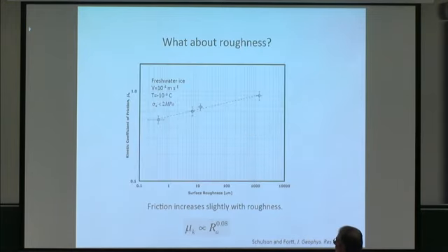There's again a certain universality. Roughness, yes, as I alluded to a moment ago, coulombic shear faults, that is, rougher surfaces, do exhibit somewhat greater resistance to sliding than a smooth, that is, a micrometer-sized roughness type interface. But this is not a strong dependence. Over 3 orders of magnitude, one gets the sense that the coefficient of friction is increasing by perhaps a factor of 2. That could be important, of course, for models, but the relationship is that the coefficient is scaling with roughness perhaps to the power 0.08. That's a fairly small dependence.